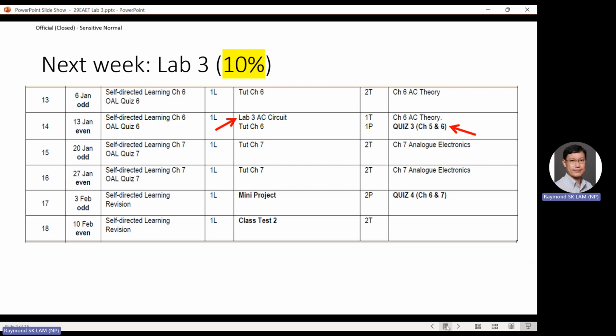It was a bit hard to understand because I thought in an AC circuit the voltage of each component doesn't equal each other, right? The source voltage is not equal. It will distribute across 2 components. So you can just take the voltage, multiply by the reactance. Actually, to be more accurate, you have to multiply using complex numbers.